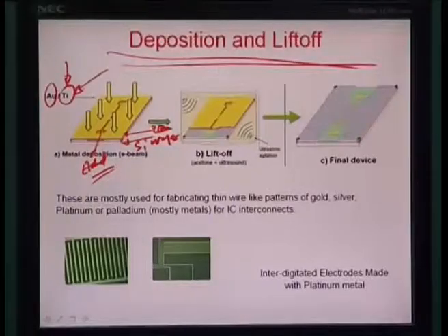building an intermediate which can bond effectively to the silicon dioxide on one side and the gold or the parent metal that you want to deposit finally on the other side. So, it creates a kind of ligand system or framework to retain a good adhesion between the deposited film and the surface. So, you have something like an intermediate layer, and this layer does not go really above a few tens of nanometers, about 10 to 20 nanometers, and then this layer can go as high as about 500 nanometers or so. Of course, it is very thick.